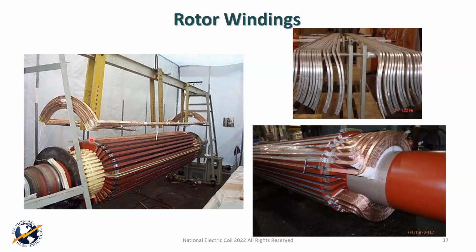Now, the coil itself that goes around that pole that creates that electromagnet on the rotor is just like a big rectangular slinky. I'm probably showing my age, and I don't know that younger folks even know what slinkies are anymore, but they're round and they go back and forth. Well, this would be like an accordion too. You could spread this out and they're all connected. This is more of an older design if it's a continuous winding. But today, much more of the coils are made, especially because of cycling, edge bent.